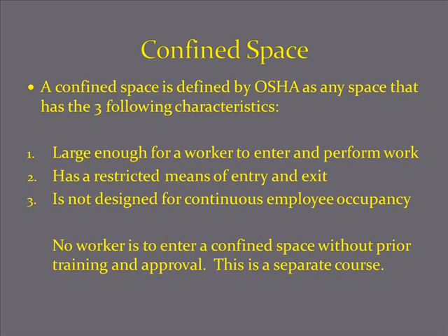The next brief subject is on confined spaces. A confined space is defined by OSHA as any space that has the 3 following characteristics. It is large enough for a worker to enter and perform their work, has a restricted means of entry and exit, and is not designed for continuous employee occupancy. No worker is to enter a confined space without prior training and approval. This is a completely separate course. Entering a confined space without prior training approval may result in your termination.